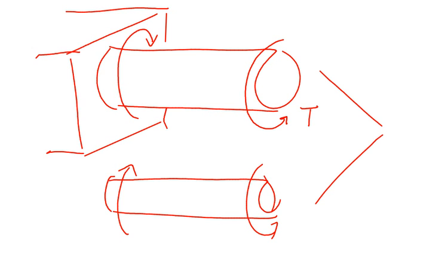Right? But when it comes to shafts, there are actually situations where we have objects that are not in static equilibrium. Okay, because I already mentioned you could have shafts that are hooked up to motors, that are part of the axle in your car and so on and so forth. So those shafts are obviously not in static equilibrium, right? Those shafts are rotating. However, the methods that we're going to talk about here actually apply to all cases of shaft equilibrium. It doesn't have to be static equilibrium. It could be dynamic equilibrium.